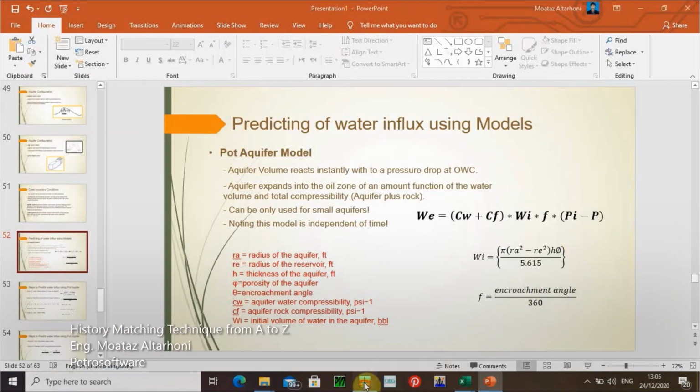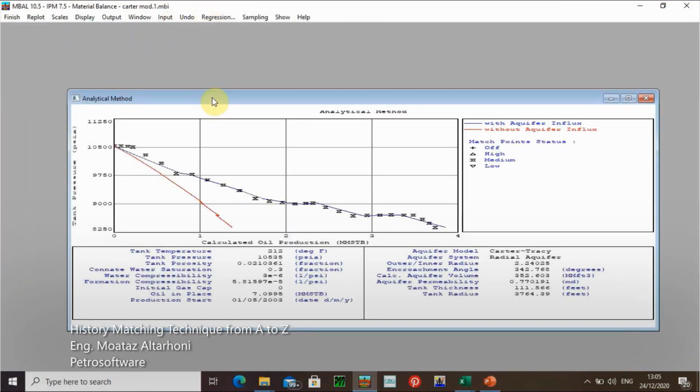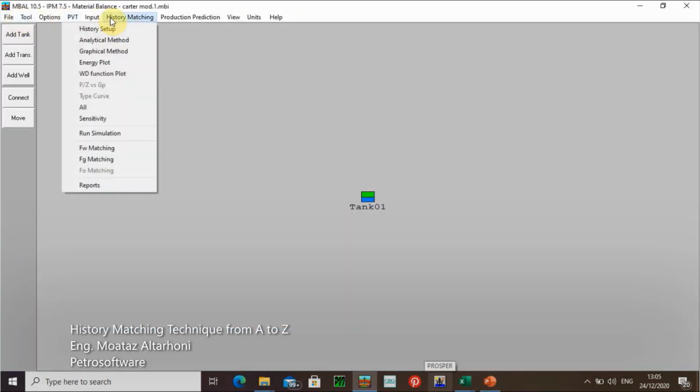If you look here in the Petro software, I got many questions about this. Assume here the reservoir thickness. That doesn't mean you need the reservoir thickness in the material balance equation; we don't see any thickness there, but I need this number to calculate the water influx. Okay, that's very important. All of these we can check again.